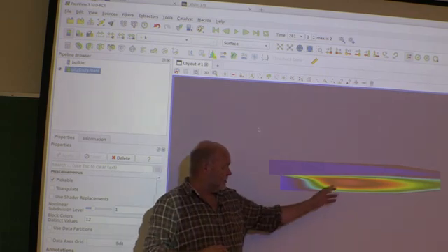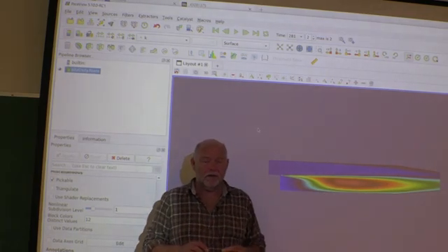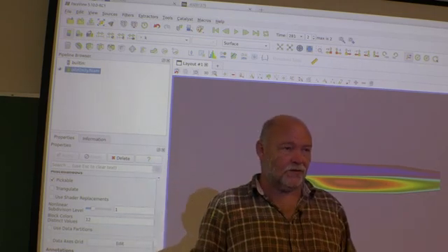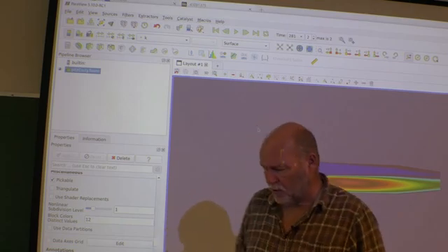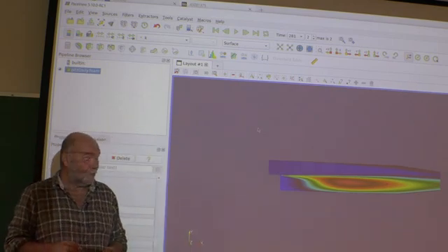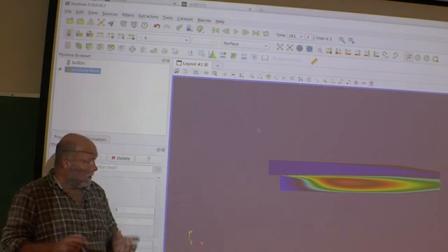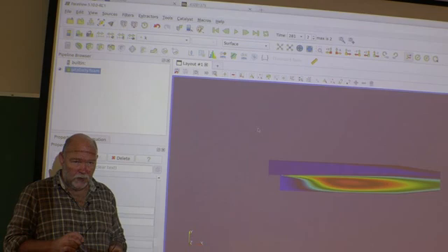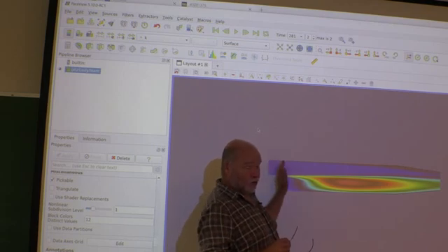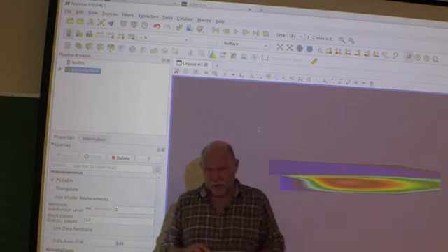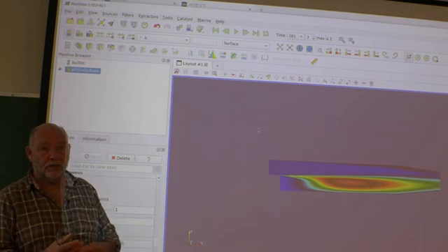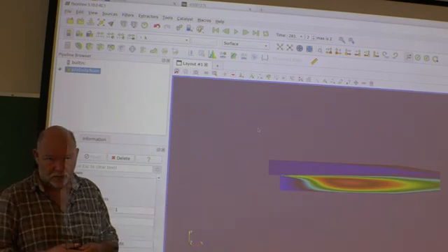So this K would then be, say, a turbulent velocity on average, actually squared. So it shouldn't be bigger than your inlet value, of course, or the bulk velocity. Depending on the Reynolds number, it may be quite big. I mean, 5.5 is not that small compared to 10 meters per second. But it shouldn't be too small either. Well, if you have a very low Reynolds number, close to laminar, well, it's going to disappear. It's going to be 0 or close.